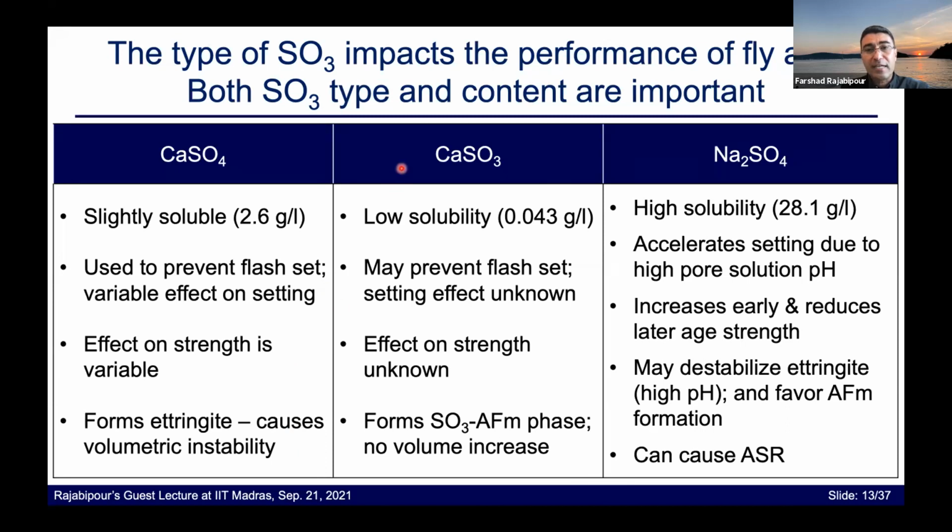Calcium sulfite, on the other hand, is a material on which much less research has been done. It's a salt with a much lower solubility. There is suggestion that it may regulate C3A, but the effects are not very well known. The effects on strength are also not known. There is suggestion that they can form sulfite AFm phases as opposed to sulfate AFm phases, and this may or may not cause a volume increase.